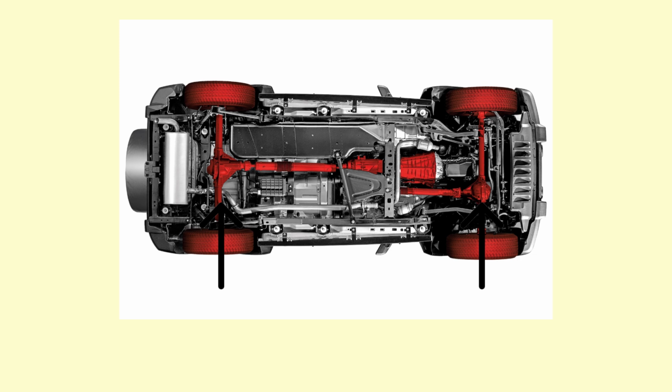Returning to the point made about replacing both open differentials, this is the most comprehensive method to reduce understeer in F4 cars, as the front and rear LSDs can adaptively distribute torque to the wheels with the most grip, which prevents the inside front and rear wheels from spinning freely and helps reduce understeer.